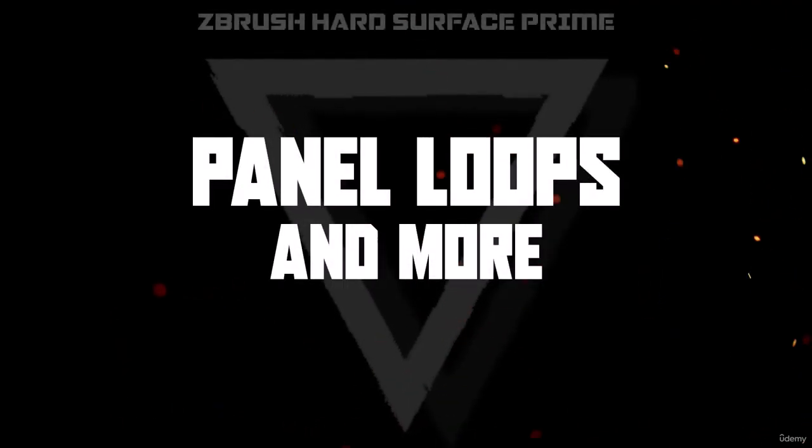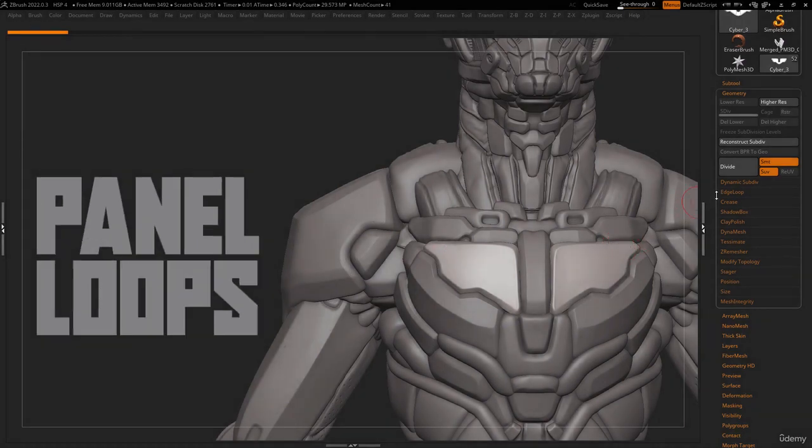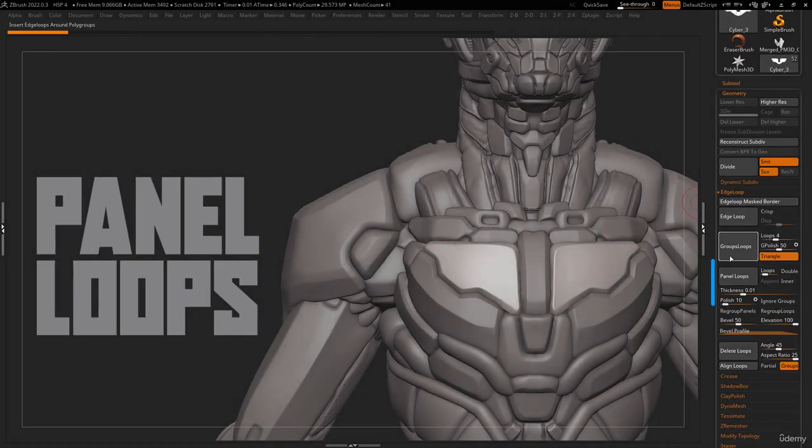Turn your polygroups into bevel panels with panel loops. Panel loops is located in the Geometry subpalette under Edge Loop tab. These are our settings. You need at least 2 polygroups to use panel loops. Use the slice brush or any other method of polygrouping your mesh.